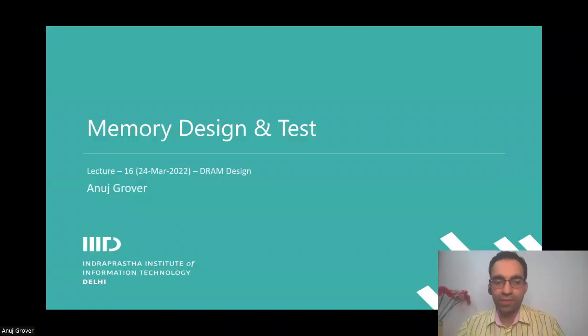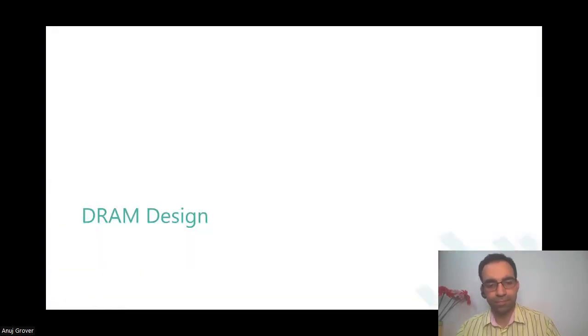So today we are going to talk about DRAMs. What are DRAMs? What is a DRAM cell? Single MOSFET with a capacitor. Why is it called a DRAM? Why is it called dynamic RAM, not static RAM? It involves charging and discharging of capacitors.